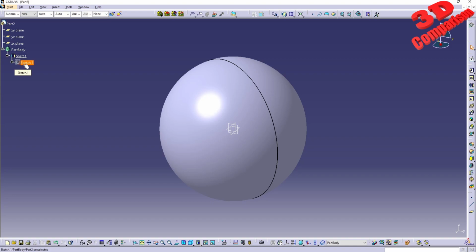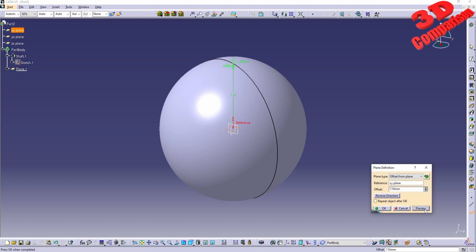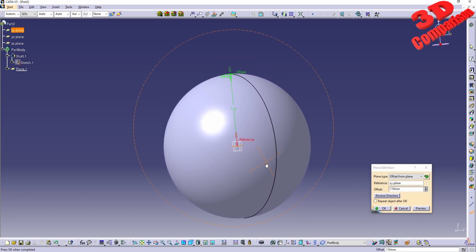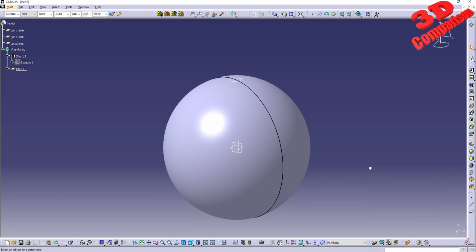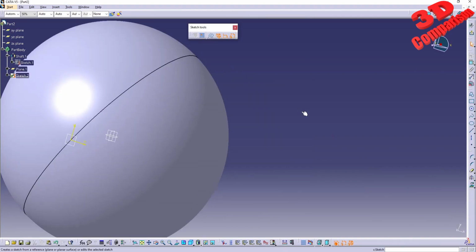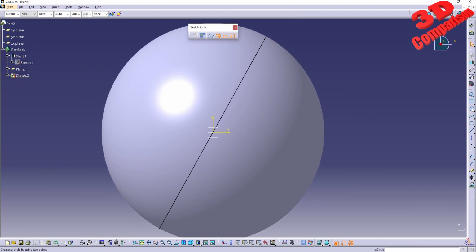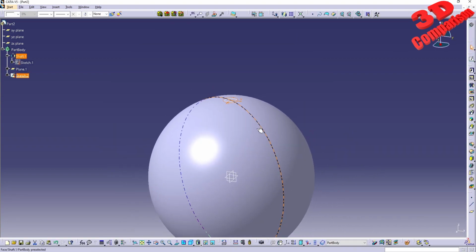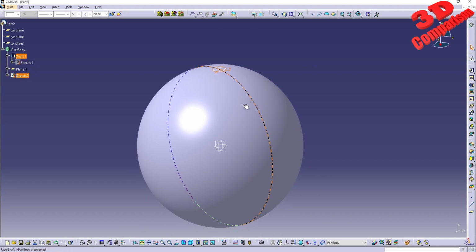And now for the Boolean operations, we can again make use of a reference plane. In this case, I know that at 110 millimeters this will be tangent to the top. And within this newly defined plane, I can create the first cutout, which will be a circle with a radius of 10. And this is the difference, let's say, between the workflows, that if I want to work with Boolean operations, I will create overlapping geometries. Therefore, I can have this padded over here.